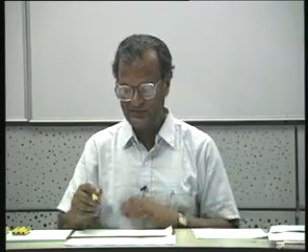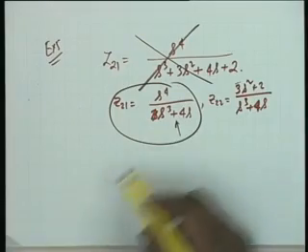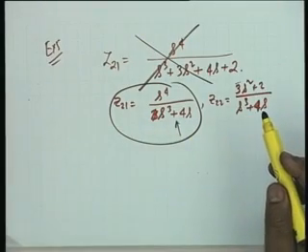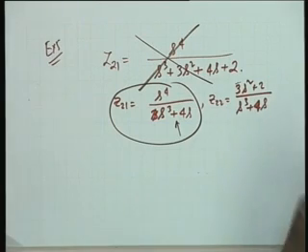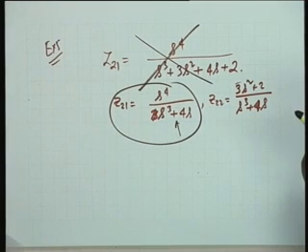But in this case it cannot have, because we are realizing in terms of two z parameters, and any pole of Z21 must also belong to Z22 as well as Z11. The pole at infinity here does not belong to Z22. Z22 at infinity is 0, and therefore there is a contradiction. So this function is not realizable. Point clear? Okay. This is one method of synthesis.